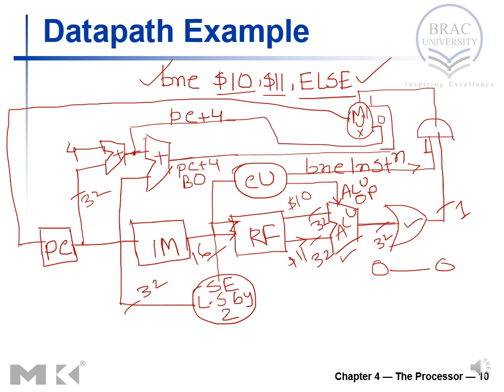That 0 goes to this OR gate, so the output, since this is a one bit output, will be 0. And since this is a branch instruction, the control unit generates an enable signal, which is 1. So 1 and 0, the output is 0. If the output of this AND gate is 0, this 0 works as a selector for this multiplexer. So when this multiplexer gets 0, the 0 input gets outputted, which means this link gets PC plus 4.